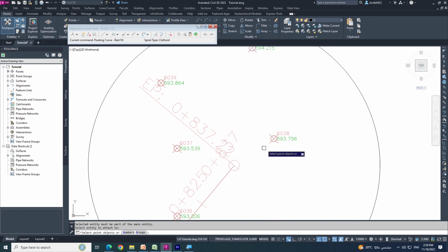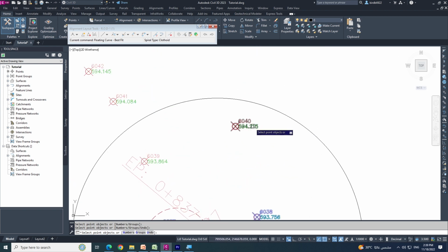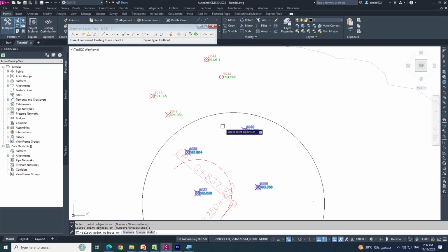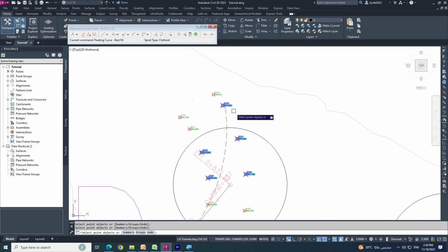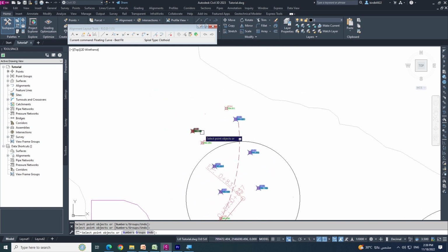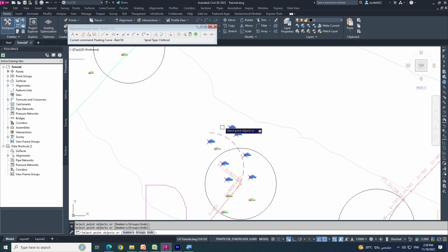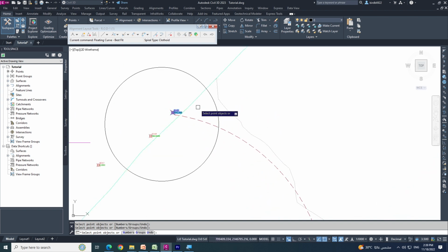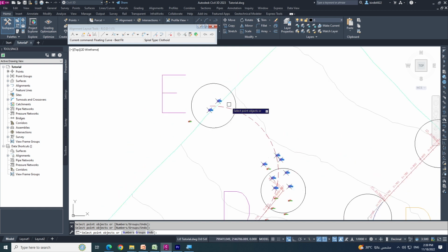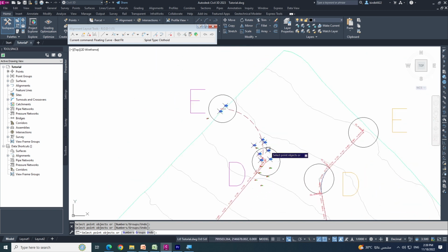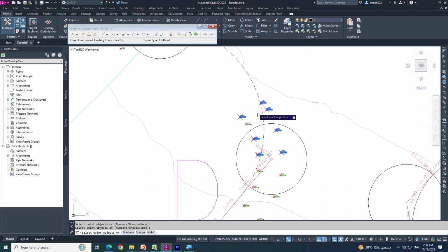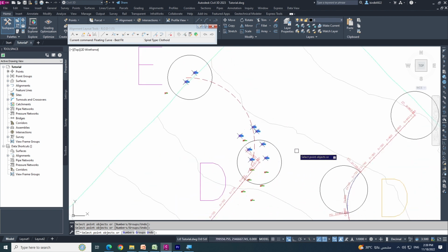I just select my first COGO point, this, and then second is that, see the line, the curve is coming, and then third point, fourth point, it will be coming, 6, I choose, no problem, and then see my floating curve is coming between COGO points. Okay, you just click enter or click